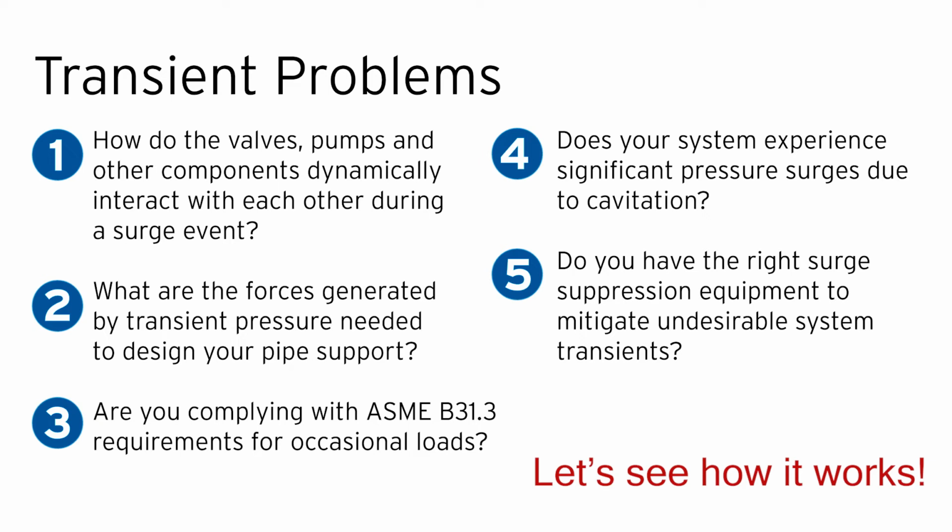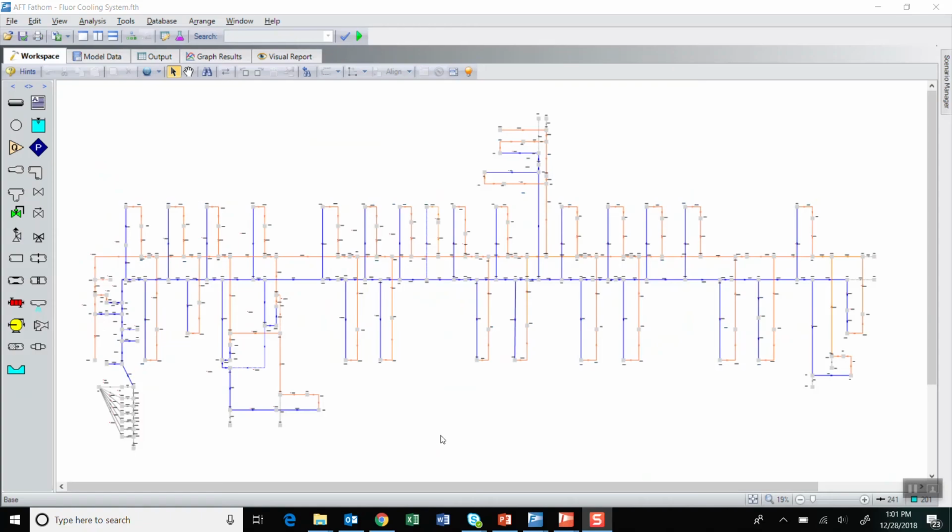by using one of the case studies from our website submitted by Fluor for our refinery cooling system. In order to size the equipment in a cooling water system, a detailed model was built analyzing the temperatures and flow rates throughout the system. Over 200 pipes and junctions were used to build a framework for the system, which was run in Fathom to verify the steady flow and temperatures in their plant.